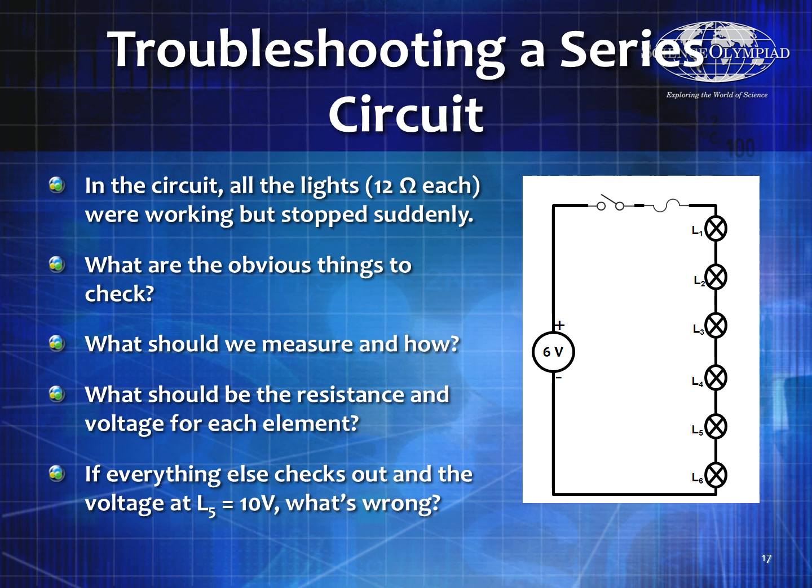Now, if I test the voltage and the only thing wrong is that the switch is open or somehow the switch is damaged, I'll get 6 volts across that switch. Okay, and so wherever I get the 6 volts across, that's going to tell me that's where my problem is. But nope, I get 0 because it's closed and it's short. Well, you know what? I'm going to look over at that fuse and see if I burnt out the fuse.